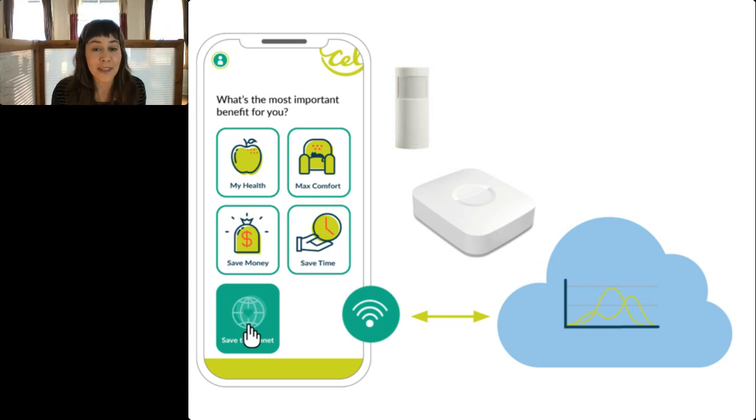If saving money is a big initiative, we want to check in with people and say, if saving money is a big motivation, are you willing to sacrifice some comfort at times in order to reduce that bill? In the case of water heat, we say, would you take a cold shower? But in space heat, it's more like, can you deal with half a degree centigrade? And how does having a really flexible device like water heat allow us to then take less draconian measures when it comes to some of these other devices?